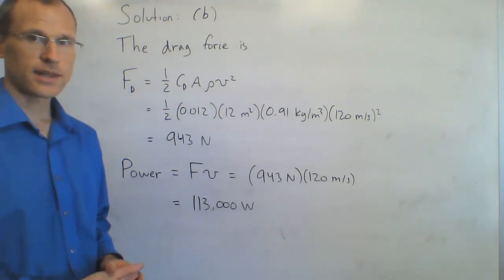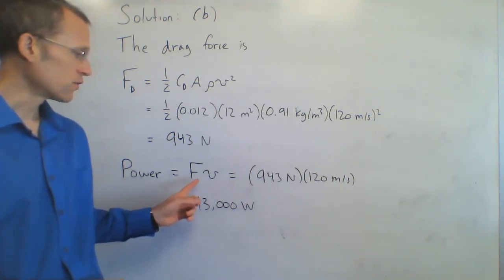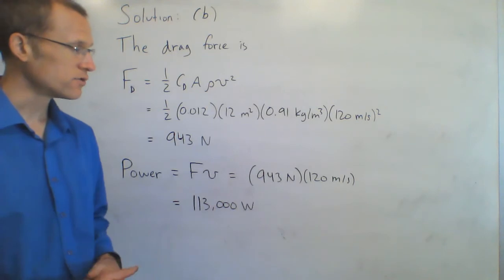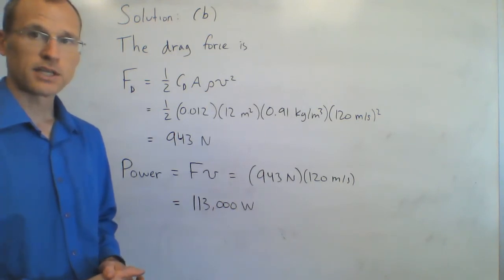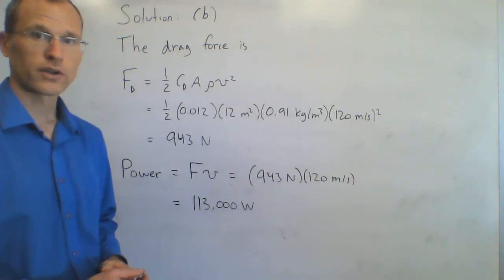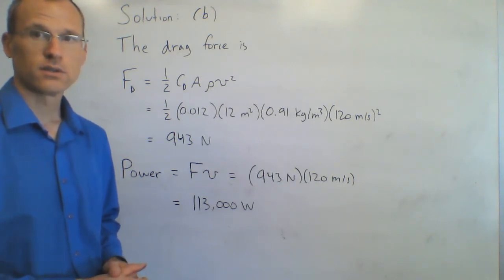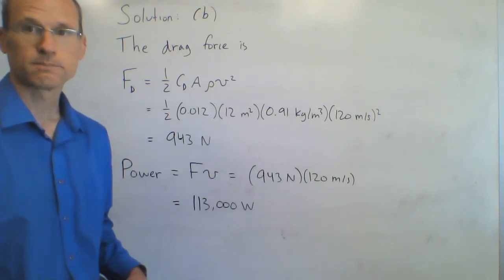And as I said, for the power, take that drag force multiplied by the velocity, so 943 newtons times my speed of 120 meters per second gives a total power required of 113,000 watts, or 113 kilowatts.